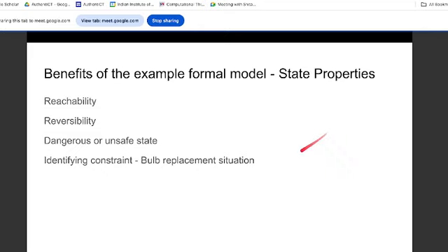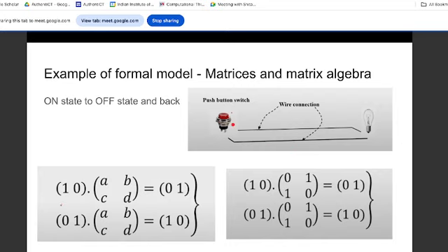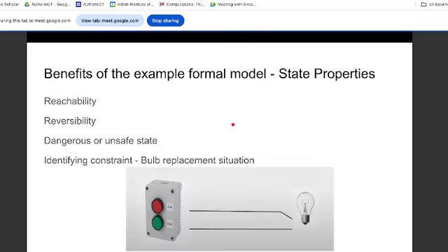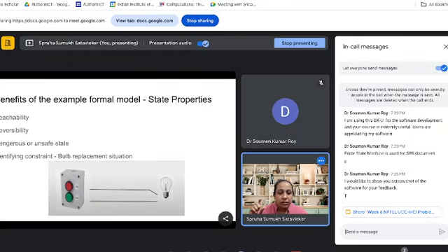An example of a solution to this problem: instead of a single push button, if there were a start and a stop, two push buttons, one would always be allocated to the switching on operation and one to the switching off operation. Then, whether the bulb was defective or not, we can identify whether the switch is on or off.